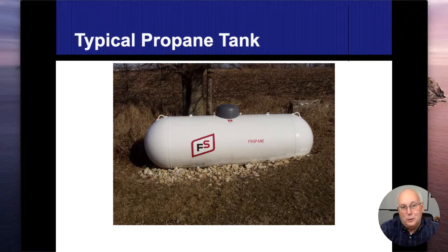Same thing if I bought a furnace that's designed for natural gas and I put it on a propane heater, now I'm going to have too big of a flame because those orifices are going to be bigger and we're going to be putting a larger pressure in there. All right.